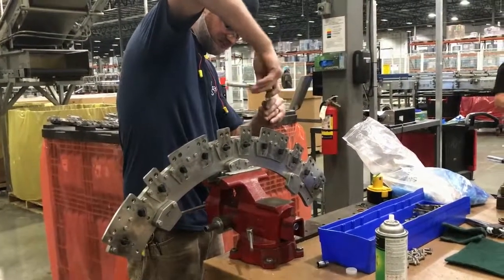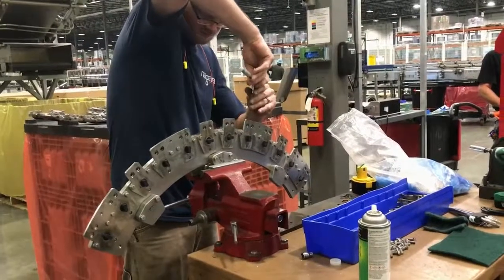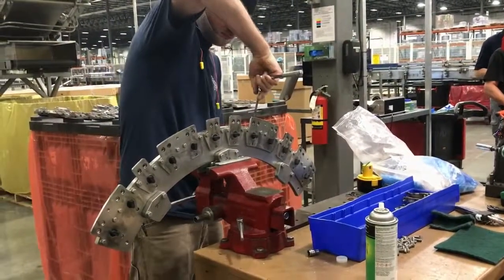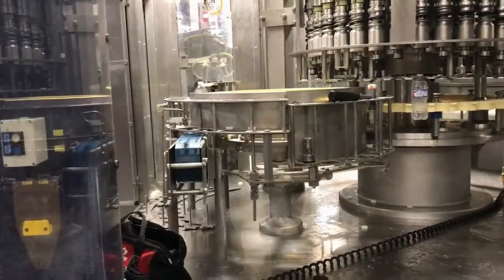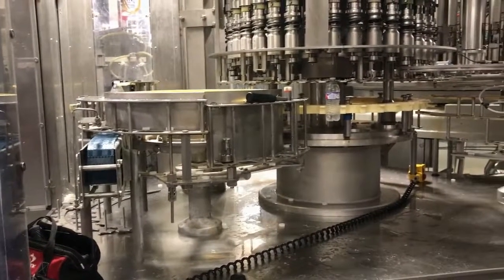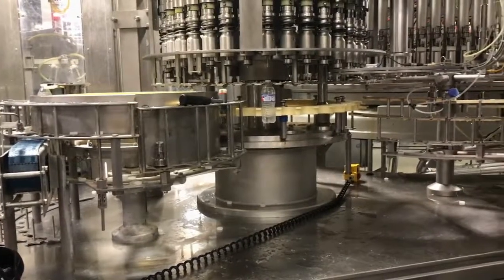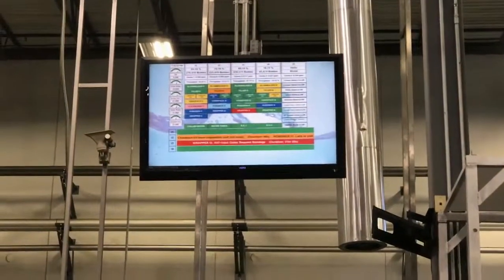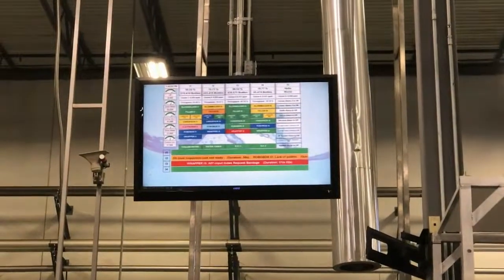Lubricants must not be applied in a manner that can contaminate the cap or preform handling systems, or that they could come in contact where the consumer will put their mouth. In the conveyors where bottles are sealed already, you should avoid applying lubricant in a way that residue will come in contact with the neck or cap of the bottle. So what happens if you think you see a maintenance problem on the floor?